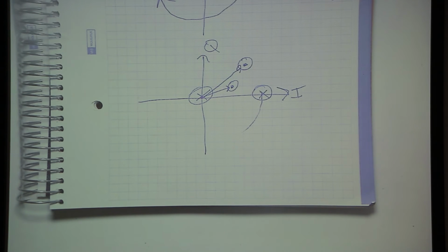As I mentioned with the HAB balloons, we use something called frequency shift keying, where they swap between two frequencies, and we see that as two different rates of spinning around the circle, which is a little more annoying to decode, so often you do it in a slightly different way. But for a lot of really popular modulation schemes, such as Wi-Fi and GSM and pretty much anything going into space, most satellites, Bluetooth, you use this IQ representation a bit more directly.